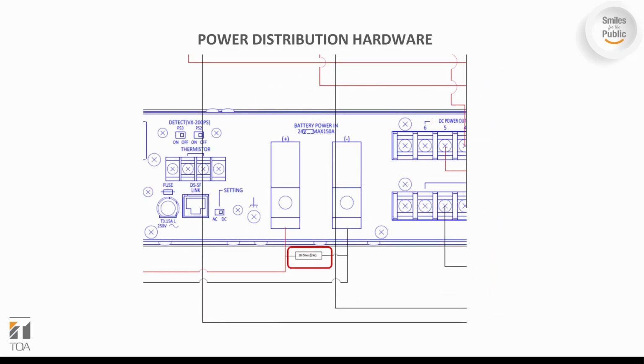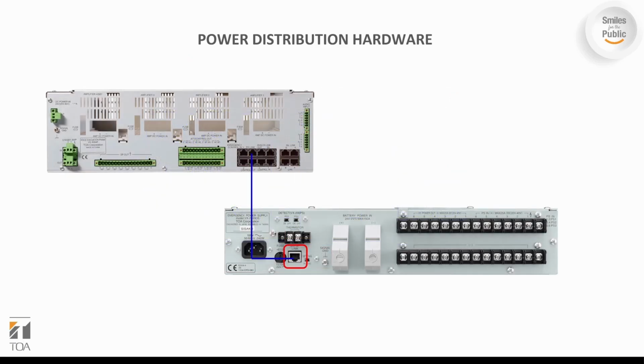Also note the 18 kilo ohm load resistor parallel to the battery. This is put in for cases where batteries fail to charge because the battery does not fit the detection parameters of the VX2000DS. Adding this load resistor allows for the resolution of this issue. In order for the VX3000 to do its monitoring duties, it must be connected to a VX3004 frame via a DS-Link.